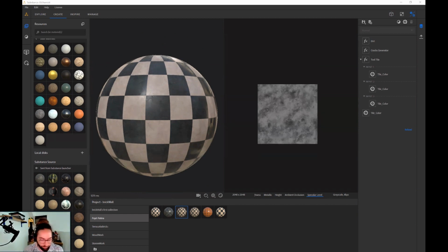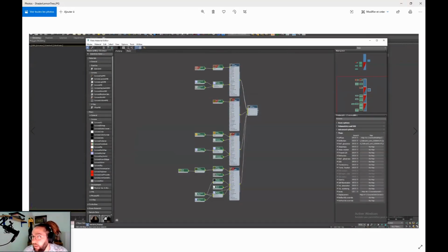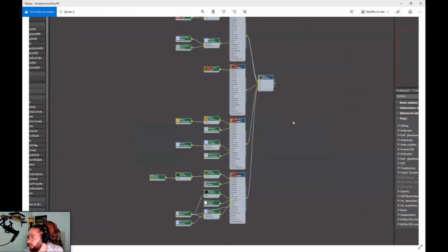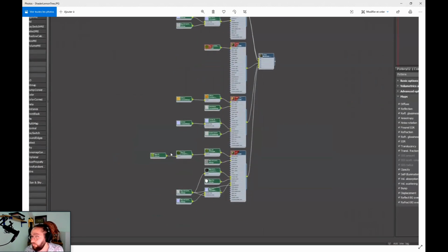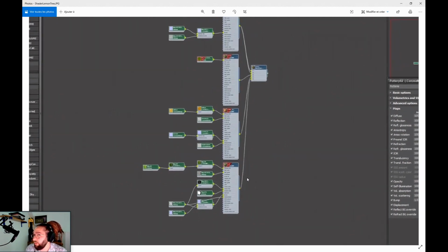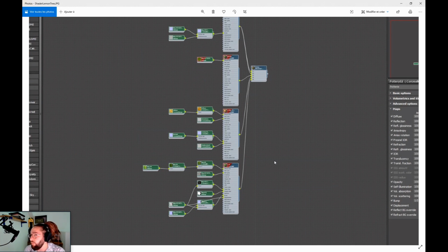Actually, I have a capture of my Max scene. I ended up exporting a JPEG, and after that, adding it on the proper slot, and that's it. From the lemon tree, I think the leaves are somewhere around this one. I came up with the normal bitmap, a little color correct to adjust the color for me, and the opacity and the normal bump, and that's it. I drag and drop all the exported maps onto the material editor, and then relink them on the right position.